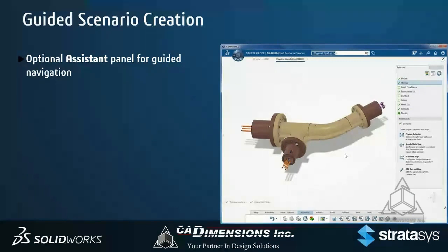We can turn on physics like laminar and turbulent flow. We can turn on things like gravity. We have full control over everything that we create in this scenario. The initial conditions depend on whether or not we have a transient step. If we have a time-dependent step, we can update our initial conditions so we know what's going on at the beginning of our solution and watch the simulation update in time that way. The boundaries, same thing. We need velocity boundaries, pressure boundaries, whatever we were looking for. That's basically our problem setup or our boundary conditions.